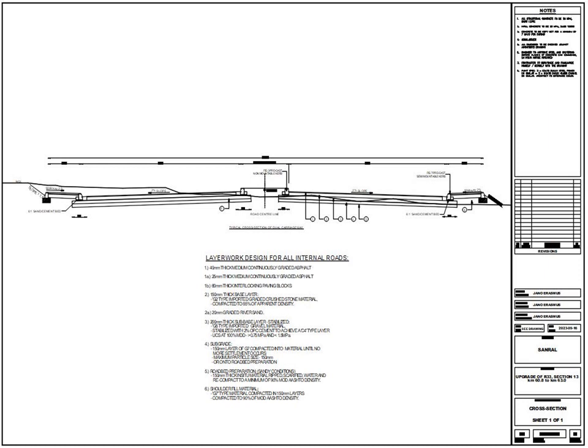The curb inlets will be connected to stormwater pipes of a minimum diameter, and will be below the road level and drain the stormwater on the western side of the road. More detailed stormwater studies and design will be done further through this project.